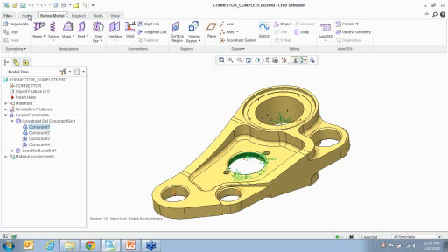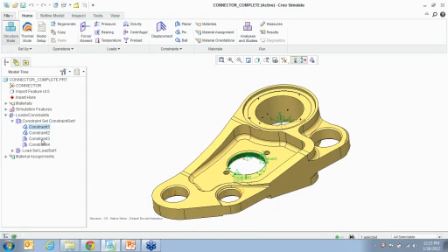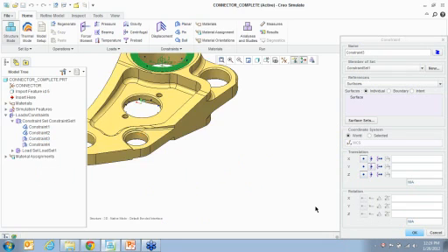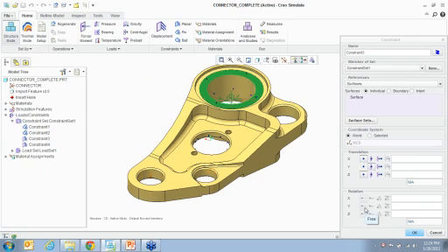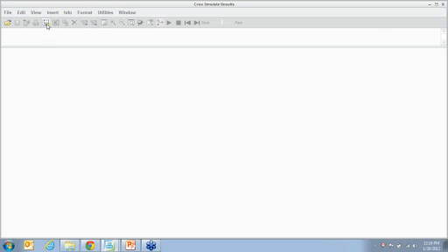You also have another deal right here which talks about the force loads. So again, over here you can see how the rotation is blocked out. So in solids, if you want to create a motion where you want to allow the part to spin a little bit, then you might want to create a pin constraint. You also have a ball constraint. You also have a planar constraint. A planar constraint just works as if the surface can translate or rotate in a plane, but it cannot move away from it. So planar, you have ball constraint, you also have pin constraint. So these are new. So let's go check out the results for this particular analysis.